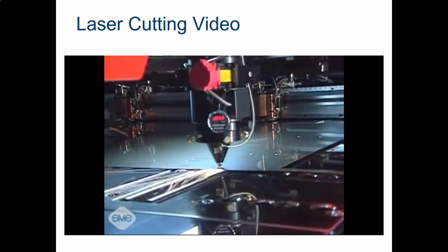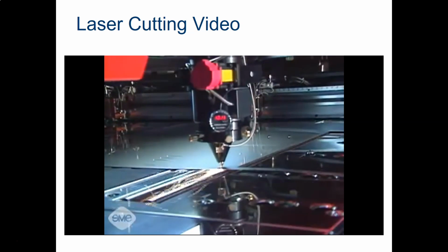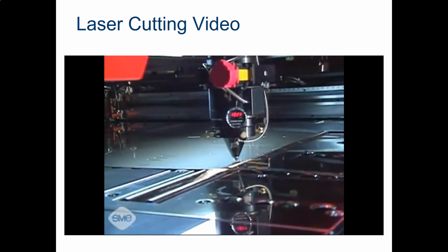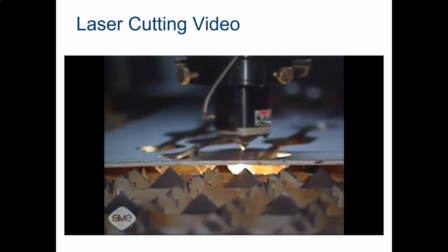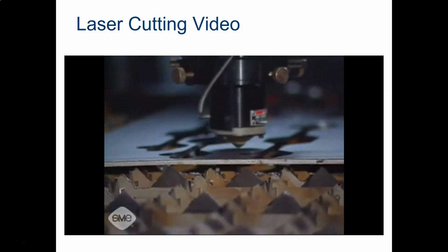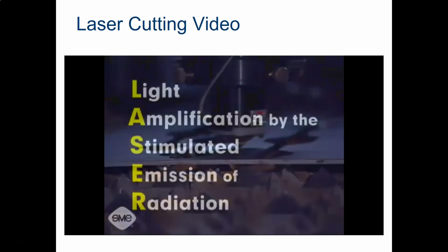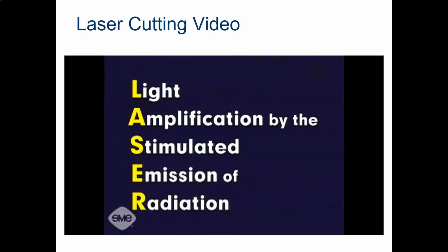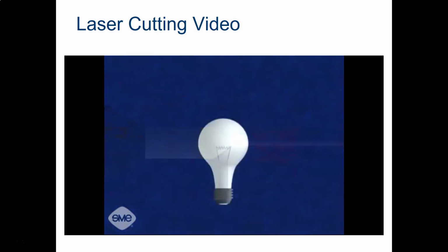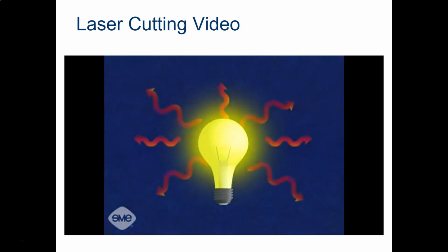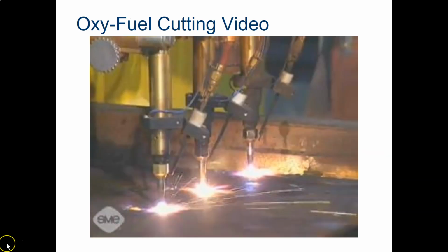Laser cutting also has limitations. It is expensive and generally cost-effective only for materials up to 1/2 inch or 13 millimeters thick, though thicker materials may be cut. The term laser is an acronym for light amplification by the stimulated emission of radiation. A laser produces an intense beam of coherent light, as opposed to ordinary random light. I'm fairly confident that you're familiar with laser cutting, but you may not be as familiar with Oxy-Fuel cutting.